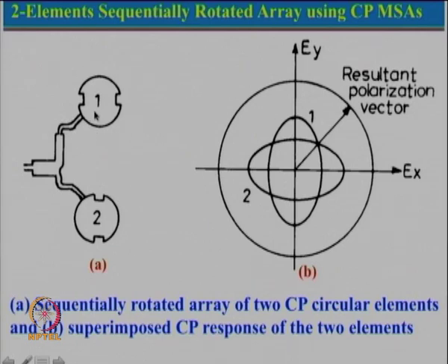Now, at that particular point here this patch is rotated by 90 degree. So, at lower frequency now the dominant will be this particular dimension. So, that would give us the elliptical shape like this here, which will have a major axis along this one here and minor along this here. So, dominant radiation is in this direction.